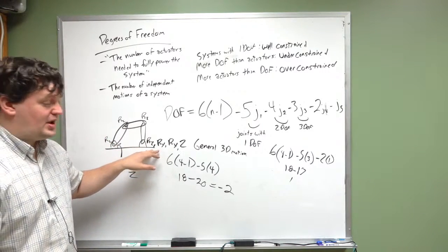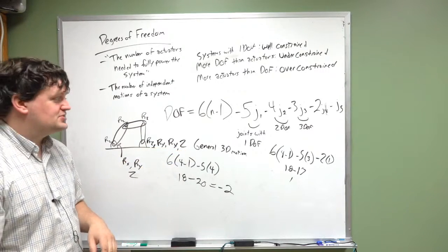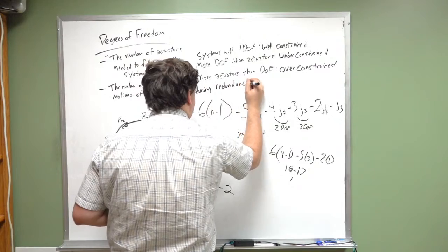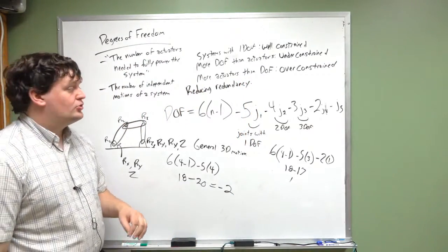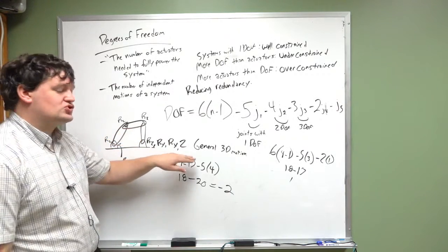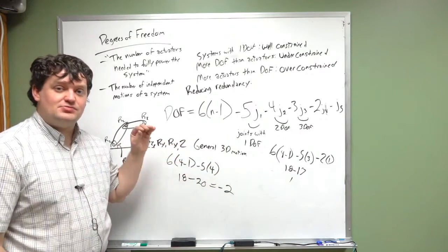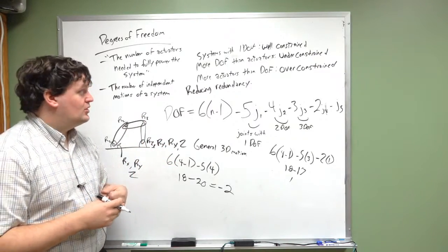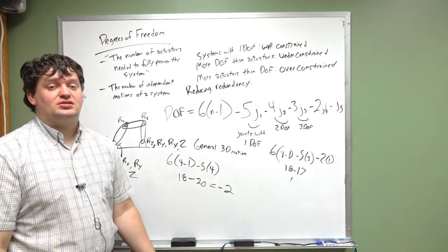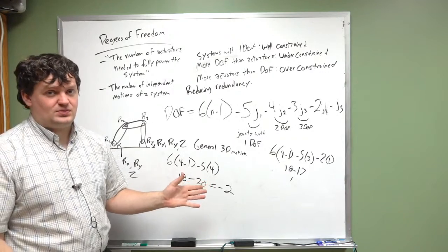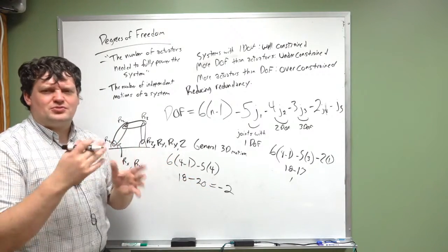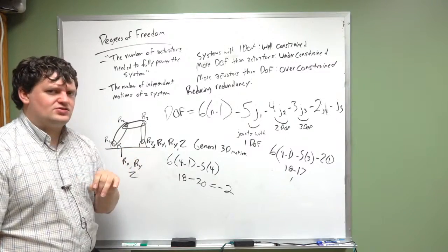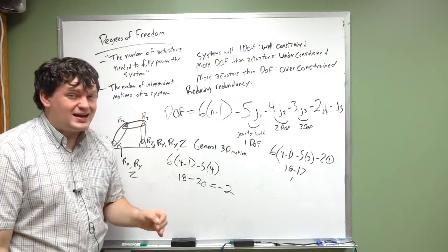What I'm doing here by adding these degrees of freedom to the system is I'm doing something called reducing redundancy. In linkages, redundancy refers to any time when you have multiple constraints acting on a system and prevent movement in a certain direction where those multiple movements are unnecessary. Redundancy is a major issue in machine design. Theoretically, redundancy doesn't exist because we can draw linkages where they're multiply nicely constrained, etc. But the issue is, in reality, having multiple constraints on the same component can cause dramatic issues.